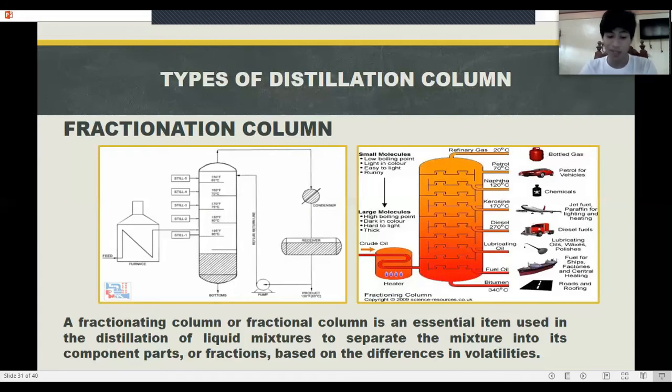Fractional distillation is a process by which oil refineries separate crude oil into different, more useful hydrocarbon products based on the relative molecular weights in a distillation tower. The fractions at the top of the fractionation column have lower boiling points than the fractions at the bottom. All of the fractions are processed further in other refining units.